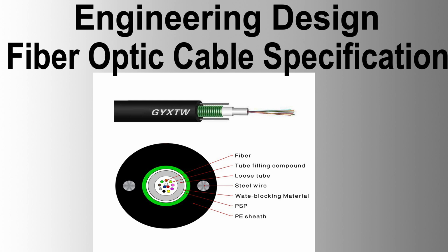Splicing chamber and splicing boxes. Provision and installation. Provide splicing chambers where required to house the splicing box and overall cable length. Install splicing boxes and marker posts for the chamber. Splicing chambers should protect the splicing box and be installed underground. Ensure splicing enclosures are rated for service in manholes, designed to prevent water and vermin ingress, and suitable for continuous submersion in water up to 5 meters deep, IP68 rating or equivalent.